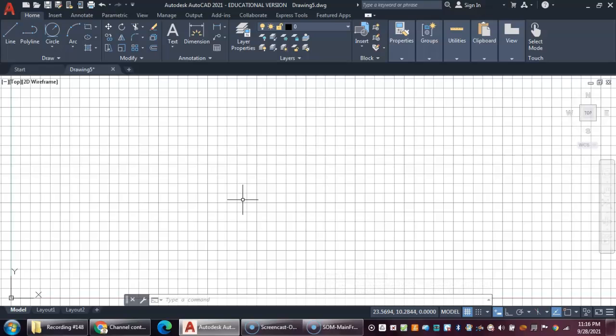Now we need to take a look and make some decisions on how to go about actually drawing this out. The only thing that I can tell at the moment is the hole diameter and some hole placement. I see half-inch radius holes, or 1-inch diameter holes. They're 2 inches apart in the Y, and 3 inches apart in the X dimension horizontally.